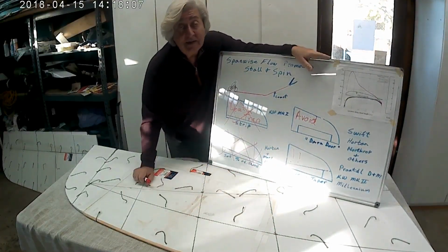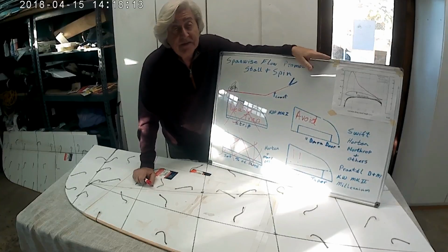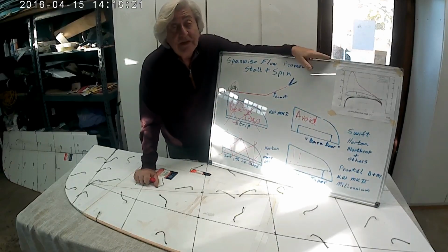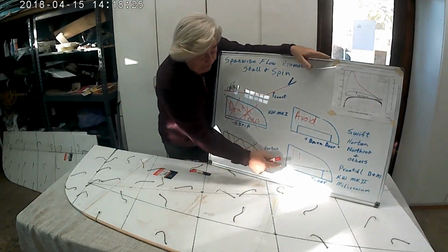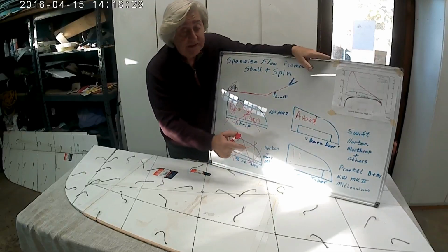And the fact that these people have flown models of these planes before they built them is meaningless. The Reynolds numbers are not the same, and as we've seen with my work, Reynolds numbers are fooler. My model flew fine. You get into full-scale Reynolds numbers, you got a problem. So, reverse taper elevon for the flying wings that are currently in work.